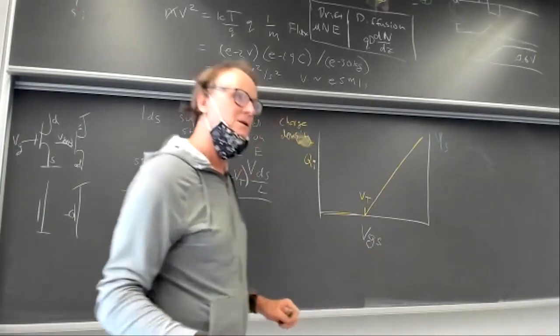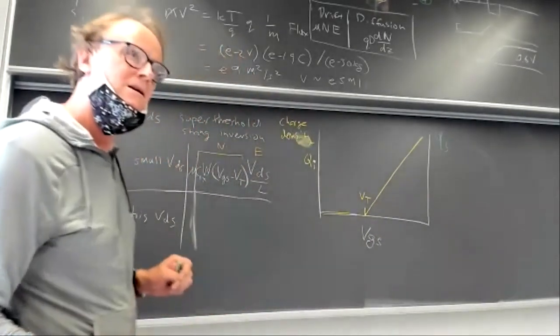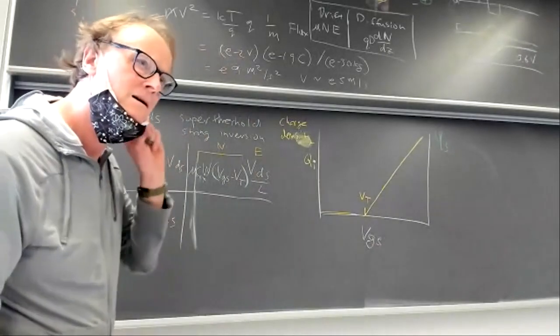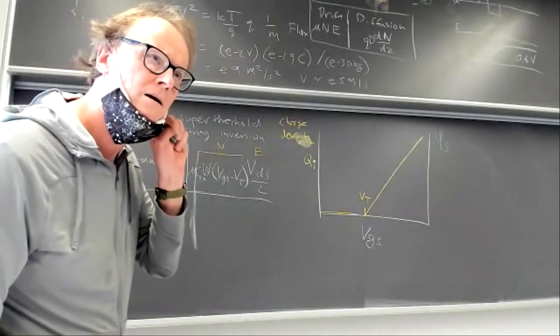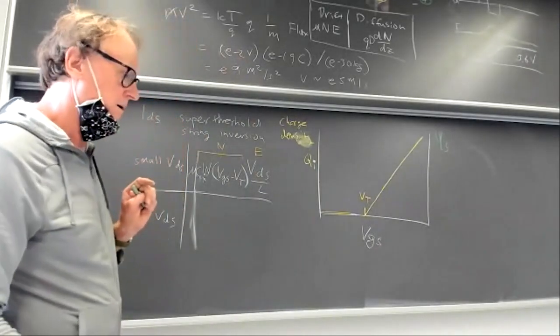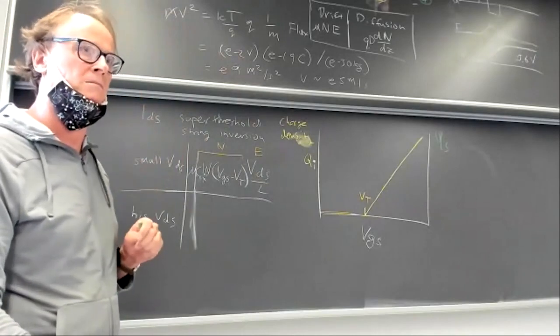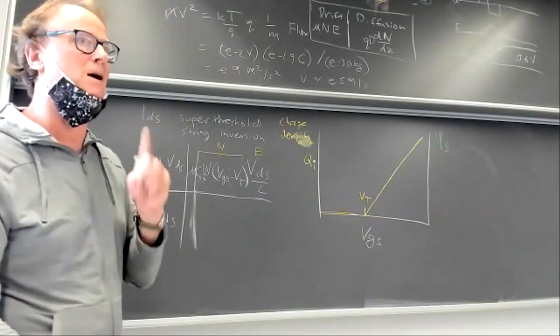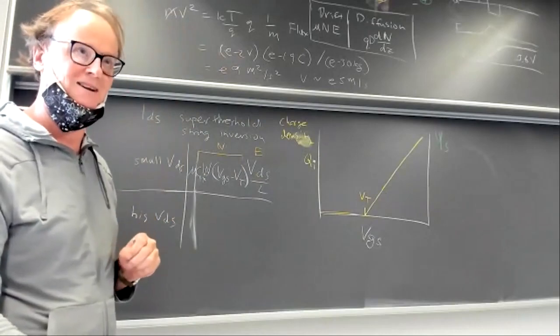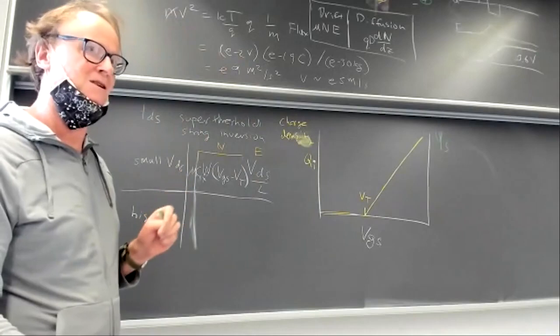The threshold voltage you're mentioning is a property of the material that you're using, right? So the question is, is the threshold voltage a property of the material? Yes, exactly. It's a property of how much you've doped the channel relative to the source.